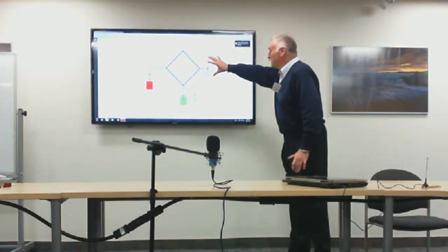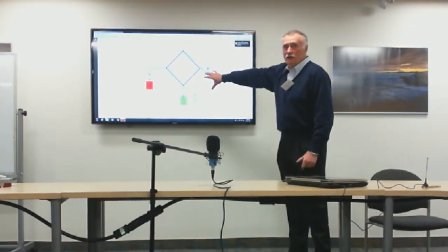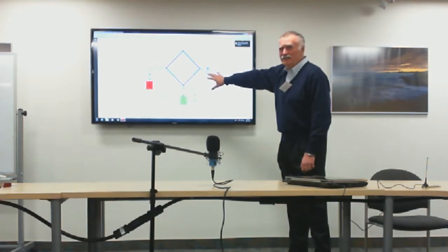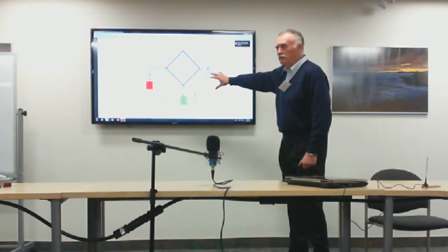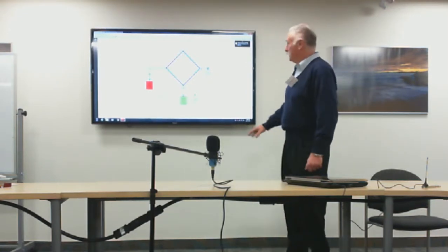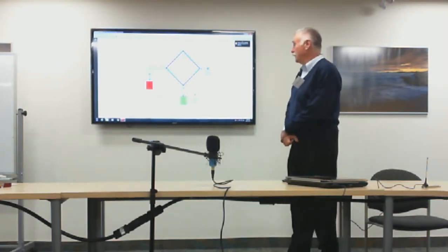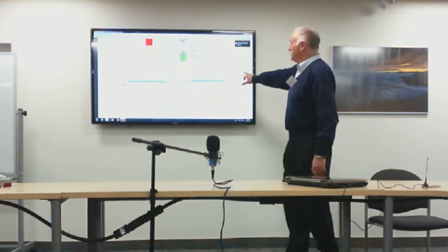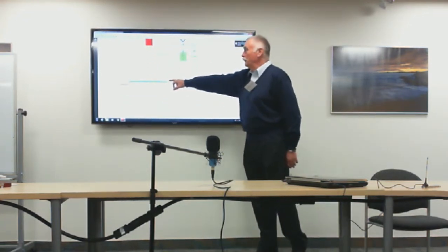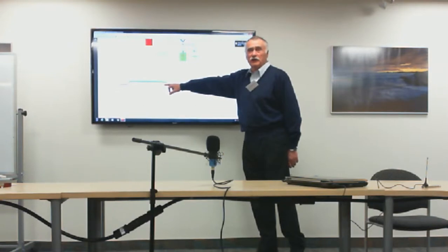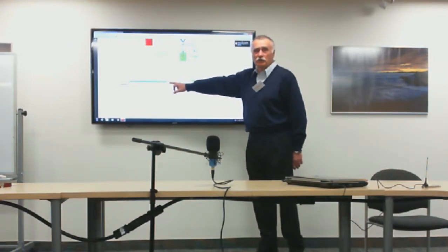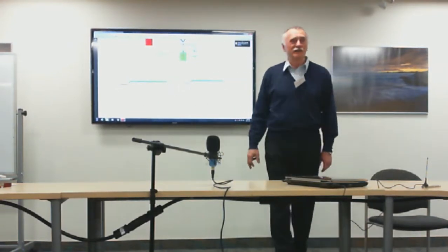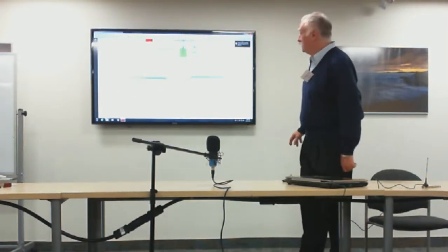So this diagram is right out of your textbook, and take a note that it works fine and all right, but it's for a single frequency for a UHF band. Okay, next please. Never mind this illustration. If you would have an impedance meter, you could test quarter wavelength and half wavelength cable sections, short circuited or open circuited at the end.